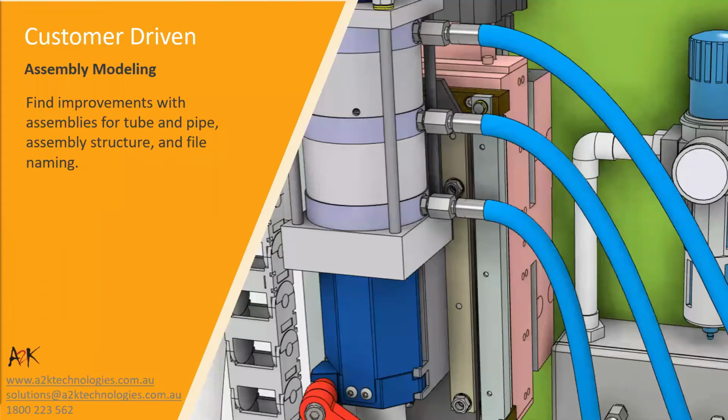Okay, let's have a look at the assembly model improvements. So in 2021, they've updated some of the tube and pipe assembly structure and the file naming conventions. So the file naming dialog box has been extended to the mirror and copy commands. There are improvements to the file naming for the frame generator and tube and pipe designs. The route command for tube and pipe now has a new property panel enabling you to rename the routes without leaving the command.